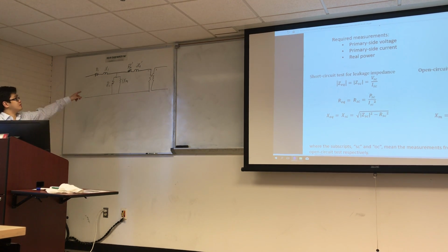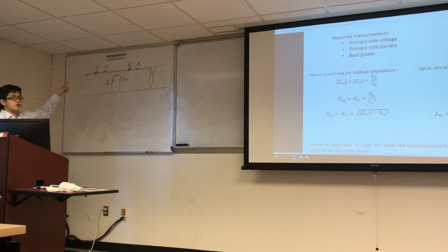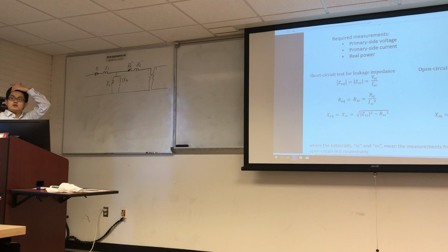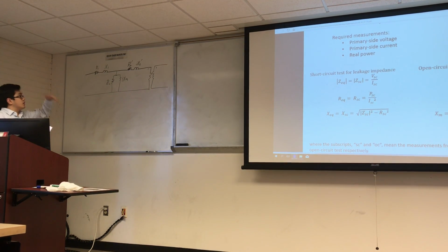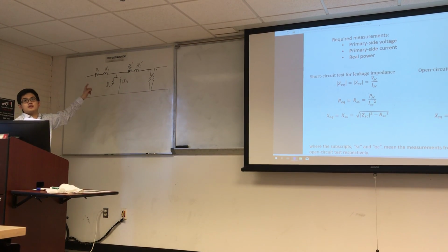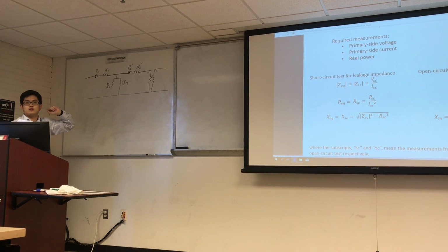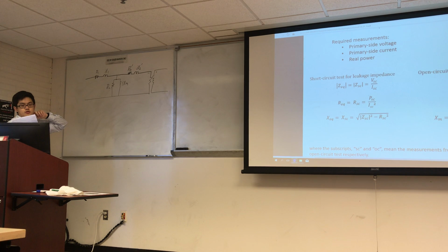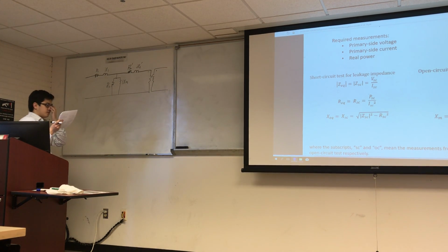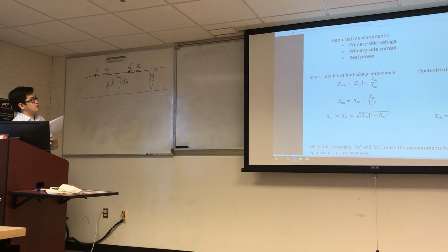Okay, so this is the single phase transformer. Right now, you have the transformer, but you don't know what the impedance of the transformer is. So how to do that? We need to use the short circuit and open circuit tests.